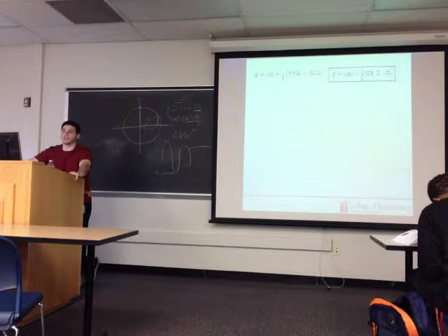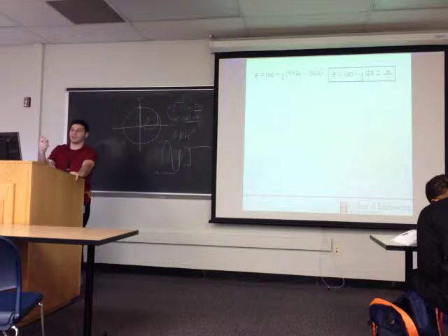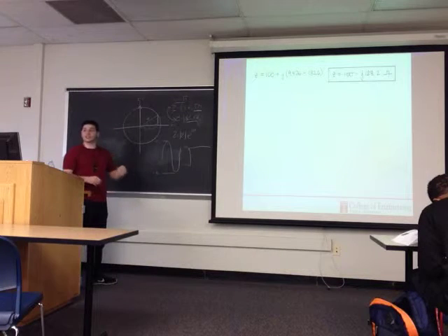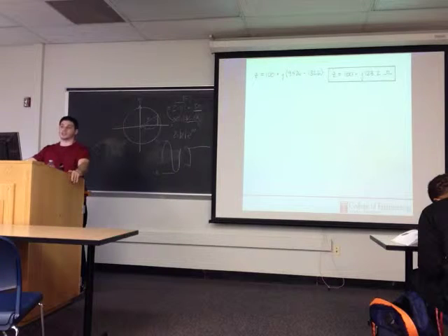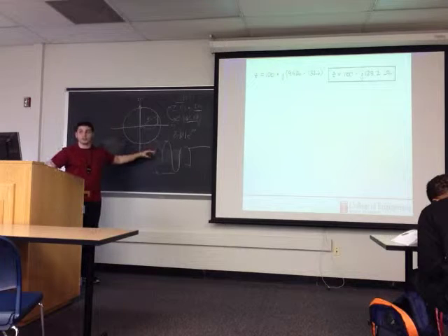It doesn't have the impedance. What it has is your inductance value, right? And your omega, you know from the frequency. If you have an AC circuit, the frequency is 60 hertz. So you know the impedance just by plugging in your equation. If you know your inductance, you can find the impedance of the circuit, knowing that the AC current is 60 hertz.